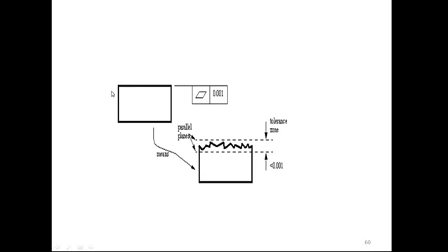So one more thing we have shown here, the flatness. How are we going to define the flatness of these surfaces? So friends, here you will understand that this is a square component, and we want to define the flatness of this surface. Flatness is shown here within 0.001. Actually, it is given as a tolerance zone. Within this, the surface flatness must be maintained. The surface of this must be within 0.001.